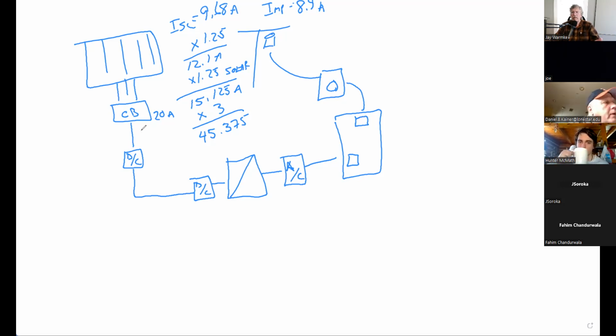Yeah, that's good theory. Because, you know, first off, when you're designing the system, you probably don't even know what equipment you're going to be attaching to it. You know it's going to be a DC disconnect, but you haven't picked it out yet. So if you go with the lowest one, it not only deals with your design, but it also deals with future changes, and you're going to be safe. But you're going to spend a little bit more money on wire.